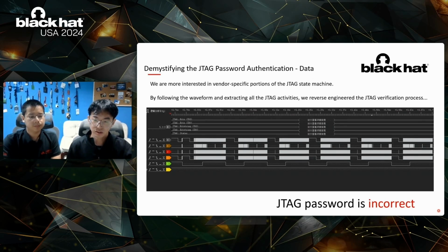We used the logic analyzer to capture the JTAG authentication process under 2 scenarios. Here we give a wrong password, and we see that the UDE debugger retries several times to connect.